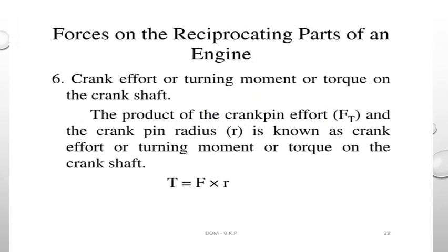Next, crank effort or turning moment. It is known as the product of crank pin effort and crank pin radius, which is the turning moment. That is, T equal to Ft into r.